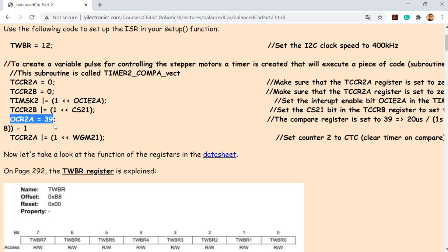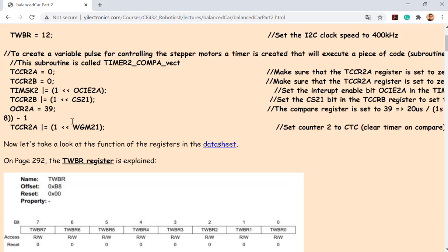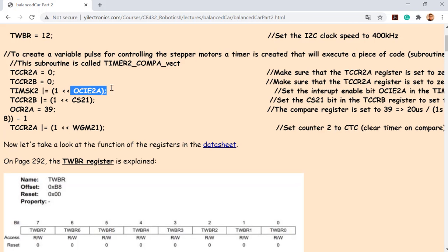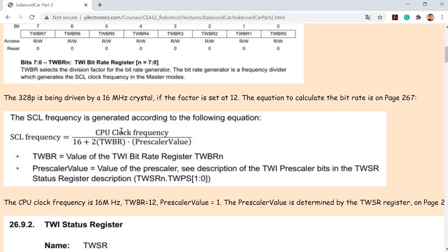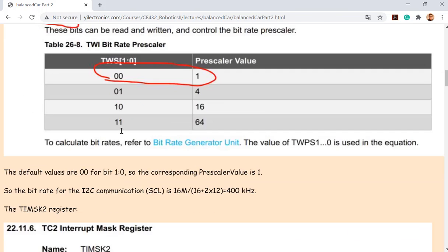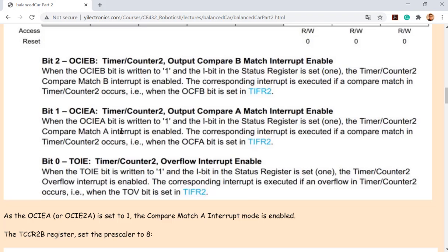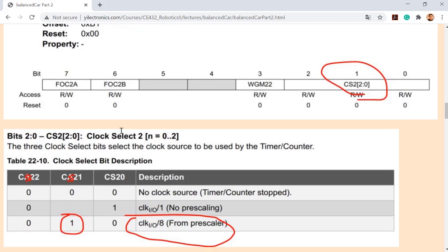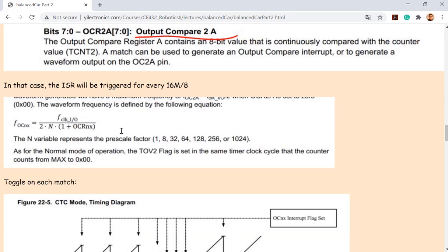But if you are using timer 1, the maximum number to count to should be 2 to the 16th. And they are the same technique, by shifting that bit. By shifting 1 by how many bits, you can set this bit in the register. I mean, really no difference. It's very simple. But here's one thing I probably want you guys to really know what's going on here.